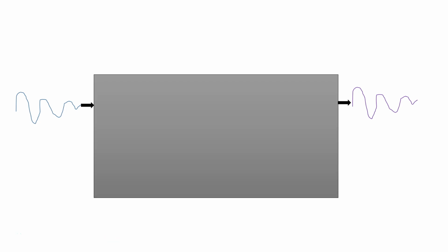All right, welcome. In this video, we will take a look at our full system implementation of an input signal coming in to our STM32 F7 Nucleo-144 board through an ADC channel. We'll grab that signal and do some processing on it. In this case, we'll spit it out back on the DAC. So we'll grab the data from an ADC channel into a processing function that we'll write, and then the result of that processing function will be sent out via the D to A converter.